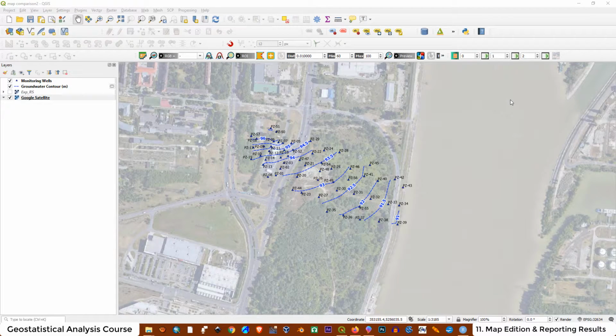The background in a groundwater flow direction map is really important, and sometimes even the background can provide information related with the shape of the contour lines. It is very important to make a map that is not crowded with information. I mean, for example, for the background, if you are going to add the CAD of the facility, don't add the labels for the name of the facilities, or even the name of the roads, because that's extra information that is not related with the groundwater flow direction.